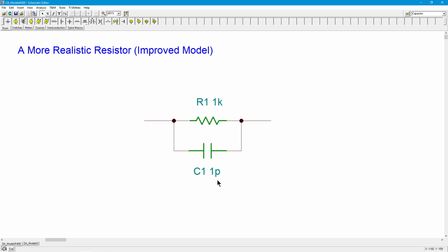So you would notice, for example, that when you go and buy capacitors, there are many, many different kinds of dielectrics that you can purchase. And they all have increasing, decreasing levels of accuracy. In other words, how well do they adhere to this abstract concept of capacitance? Right? There's going to be an equivalent series resistance.